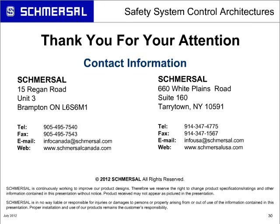EN 954 is where control categories came from. One of the misunderstandings out there is that control categories have gone away and been replaced by performance levels. That's not completely true. Control categories are an integral part of achieving a performance level. Your overall goal now with ISO 13849 is to achieve a performance level.